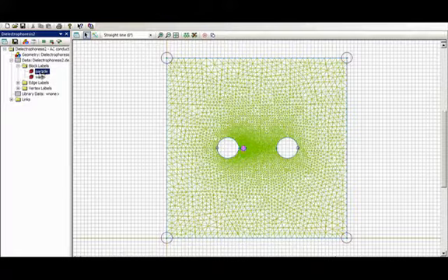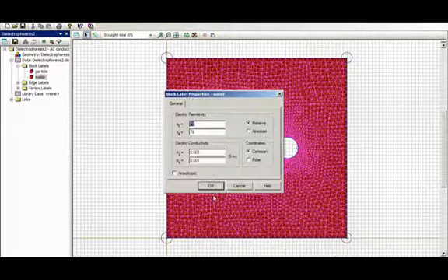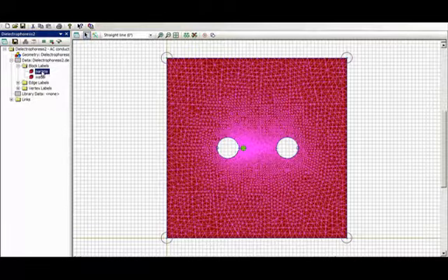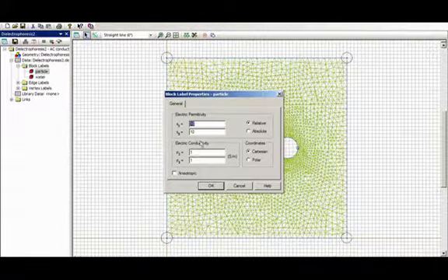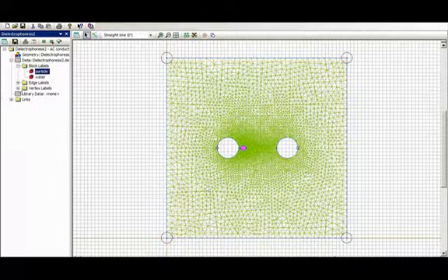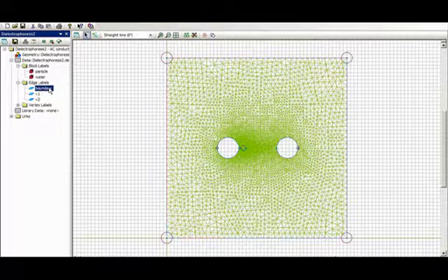For example, an axon or something with cylindrical symmetry, or a cylindrical type of micelle. This is a water region, and I've given it a millisiemens conductivity. The particle has a conductivity of 1 and a dielectric constant of 10. Now, the edge labels: this is the boundary of the solution region, and I've given that 0 potential, and I don't care what's occurring at the boundary, and really you'd like to push this as far away as convenient.